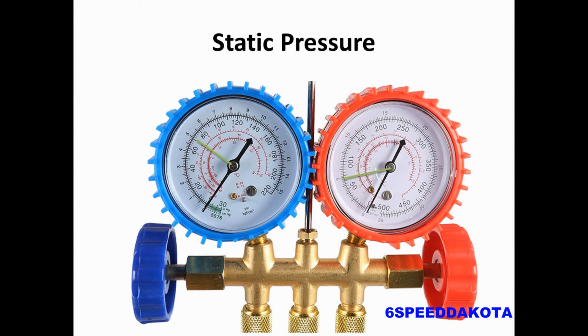building air conditioning, stuff like that. You can see if you look very closely, it does have R12 on there even. So the temperature it corresponds to on the low side is actually the evaporator temperature, and on the high side is actually the condenser core temperature. That's a little bit more for household refrigeration, but it can help you pinpoint issues if need be.